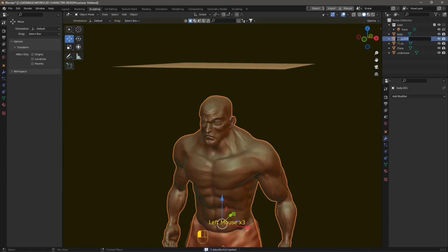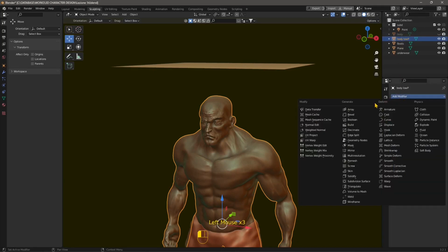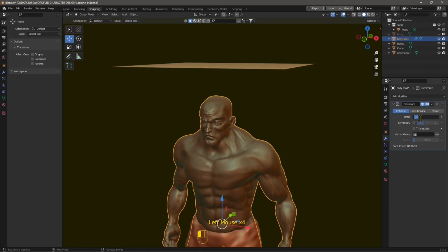To start that, we can continue also with the sculpting. You can see I've copied the body, which means the main character there, Control C, Control V, and I want to make a low poly version of this character, because when you use simulation, you don't need too many polygons, too many faces. So I want to decimate using the decimate modifier, and you can see the face count there will drop. And this is, again, really useful because you cannot run simulations with a lot of polygons. You need to start with few polygons as always, and then you increase the level of quality at will, at necessity.